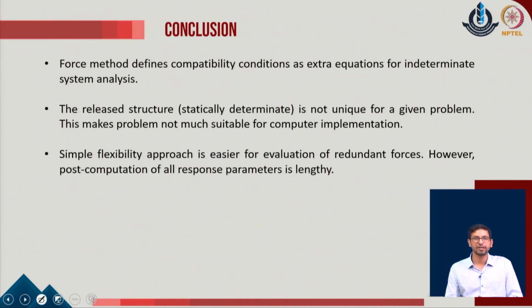So, with this we identify that the standard force method, which is a compatibility equations based system, provides the extra equations of the compatibility and solves the indeterminate system. The release system which we define is not unique, and that becomes one of the main challenge to include these kind of approaches in the computing environment.